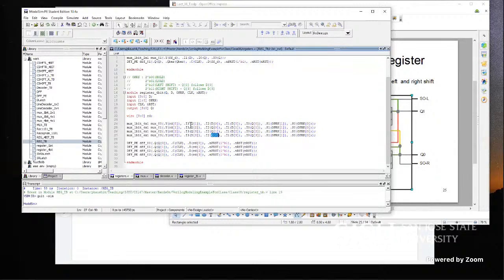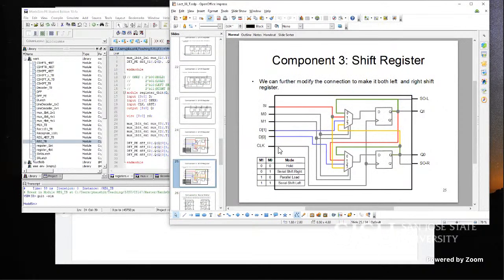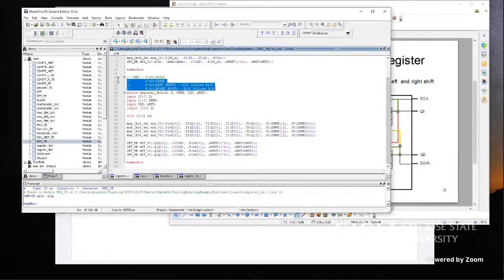And then I3 is just the reverse order, which is right shift, MSB coming onto the LSB side, and Q3 follows D3. Q2 follows Q3, Q1 follows Q2, and Q0 follows Q1. So through this multiplexer connection, we are making these operations.